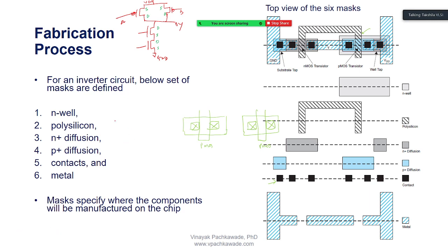Let's say I use another mask here, and there are the contacts. These are N plus heavily doped regions, and somewhere here I am using these two. So this is NMOS again, and this is NMOS again. So once we do that, how can I draw the connections?